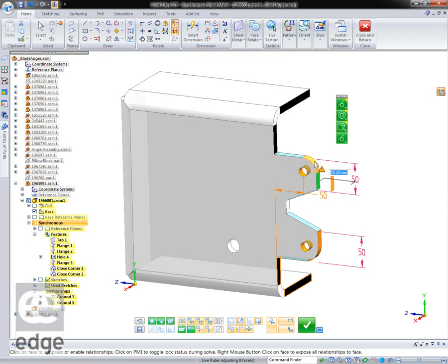So if I select a face and right click on it, I get the rules that are being applied to that face. We can see here a tangency, and if I touch on there and slide across, it will show me the relationships. You'll see when I highlight that icon, those tangent faces light up. The concentric, I'm not clicking anything here, I'm just hovering. If I go to the concentric, it'll show me what's concentric. Again, it brightens up that circle.